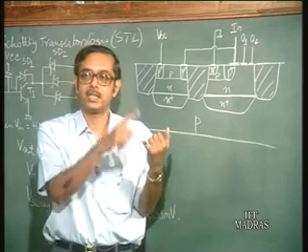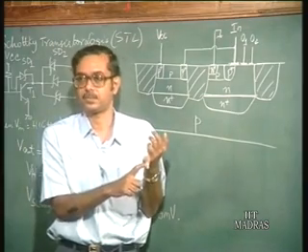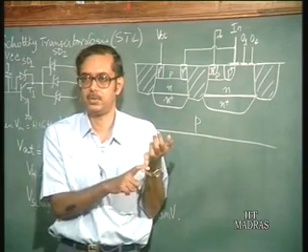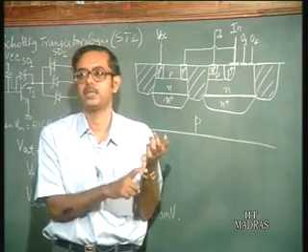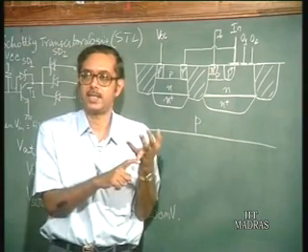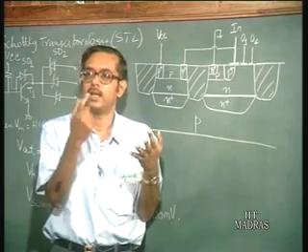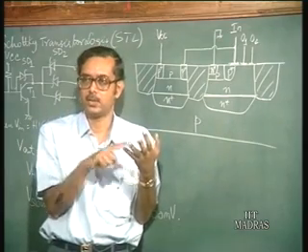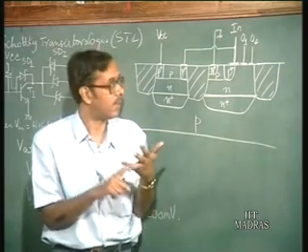Number one, it is a Schottky transistor. So, charge storage problems will be less, the transistor is not going to saturation. The logic swing is less, with the result it is going to be faster. Logic swing less means it is obviously faster.